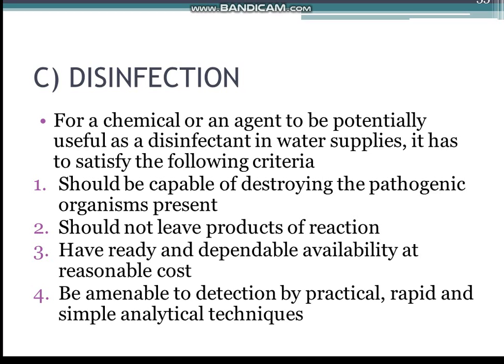Disinfection. For a chemical or an agent to be potentially useful as a disinfectant in water supplies, it has to satisfy the following criteria. First, it should be capable of destroying the pathogenic organisms present within the contact time available and not unduly influenced by the range of physical and chemical properties of water encountered, particularly temperature, pH and mineral constituents.